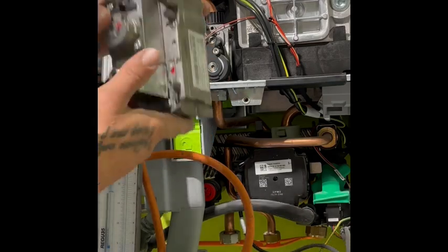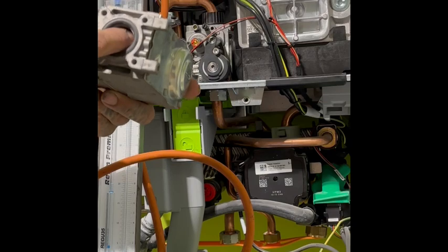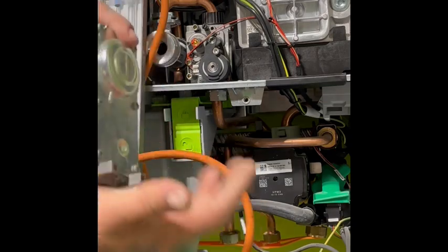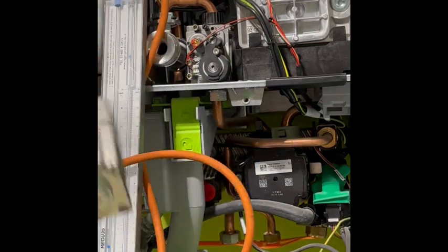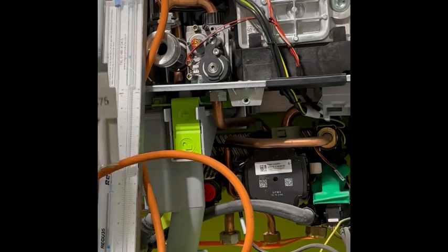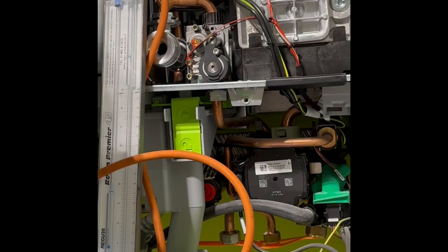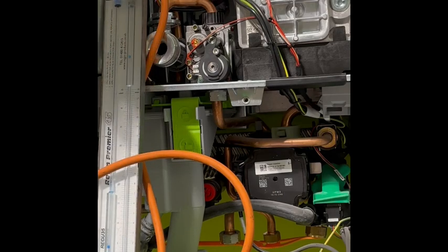So a good one to look at is always take your gas valve out, check the bottom side of it, which is the inlet side, and you'll see a bit of gauze there. Take it out, bang it, and you might see some debris drop out. That can drastically reduce the gas supply to a boiler or any appliance, but predominantly you're going to find it on a gas valve, so have some protective gauze there to stop that from happening.